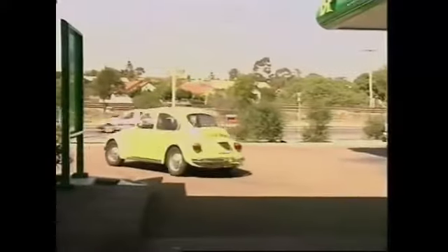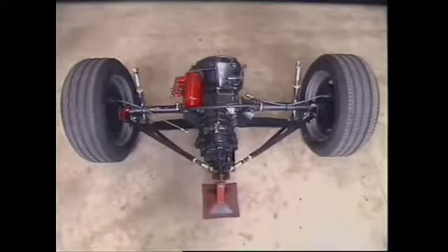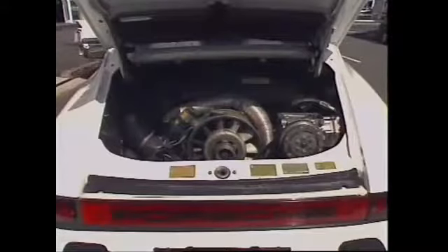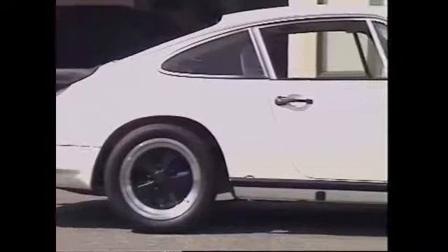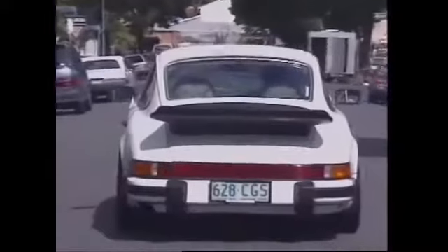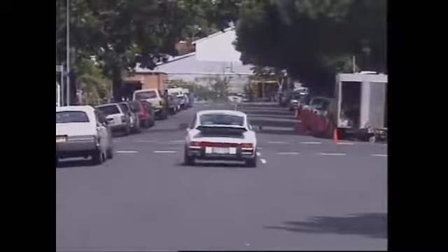This rear-wheel drive vehicle has the engine at the rear, driving the wheels through a combination transmission and rear axle called a transaxle. The transaxle is lighter than a separate transmission and rear axle. Moving the engine to the rear allows a lower bonnet line, which improves aerodynamics. The increase in weight over the rear wheels can improve their traction.